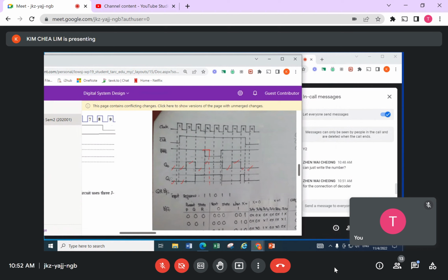Next, now we proceed. This one becomes the input to my second T flip-flop. So when things happen, my clock will see what the signal in front is. So at the second clock pulse, I retake this one. This is correct because of the clear earlier. So the second rising edge comes, I check what the input to me is.